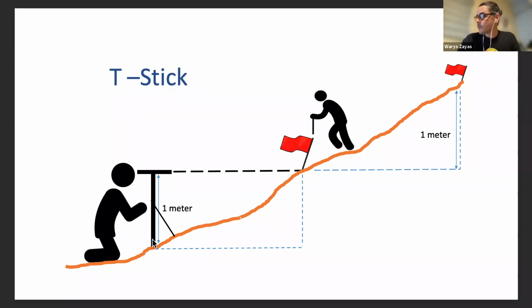And then I stop here, I look through the side at level 0 in the bubble levels here, and I see through the side the bottom part of this point. So now you are sure that you are at the right interval of 1 meter to place your contour barrier.